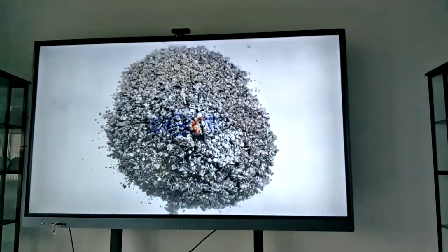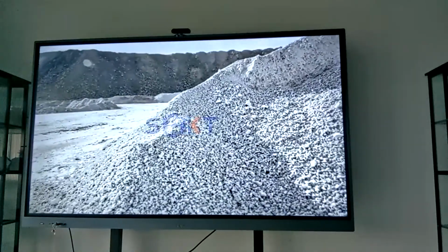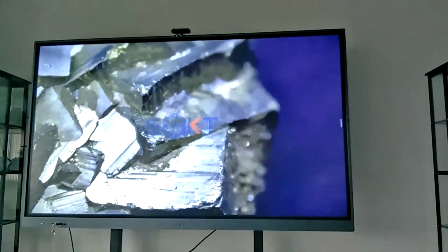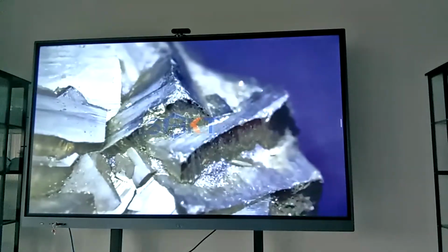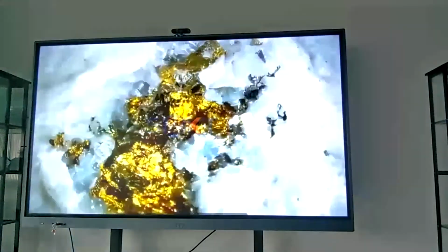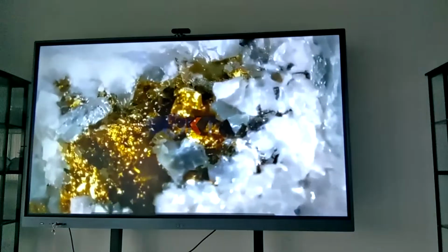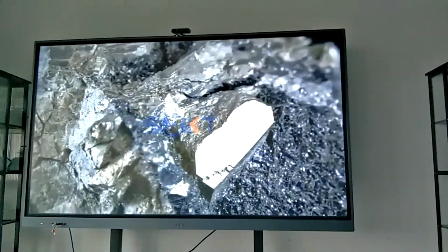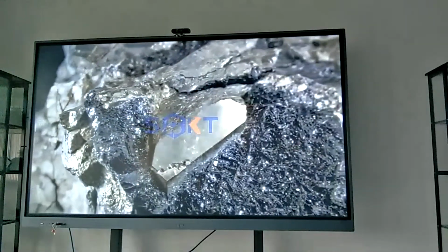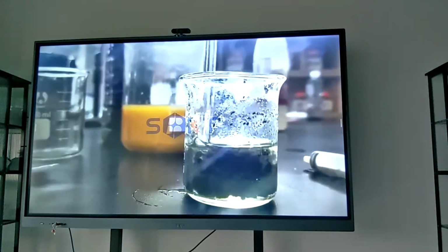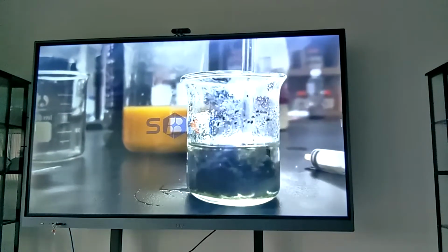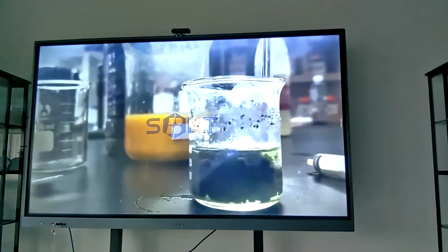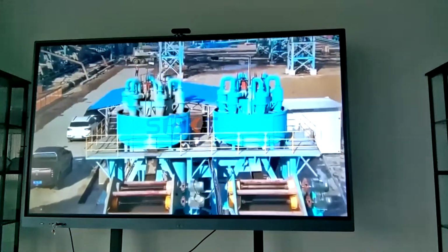Step 3 is to analyze the form of gold. For encapsulated gold, use pre-treatment and CIP or CIL. If the ore contains associated valuable elements, like copper, use flotation for comprehensive recovery.